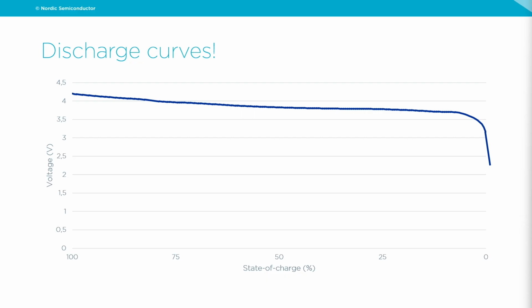They have a really flat section in the middle, and as we see, the difference in the voltage between 80% and 20% state of charge is really, really small, which makes it necessary for lookup tables to be very, very precise. Unfortunately, this curve changes with temperature. So if the lookup table was made to be very, very precise, measuring very slight differences in voltages, they get thrown off by miles when there is any sort of temperature swing. And this makes this technique inherently unreliable.